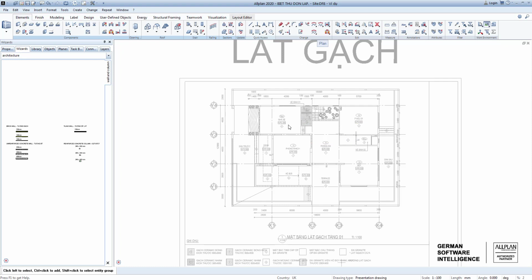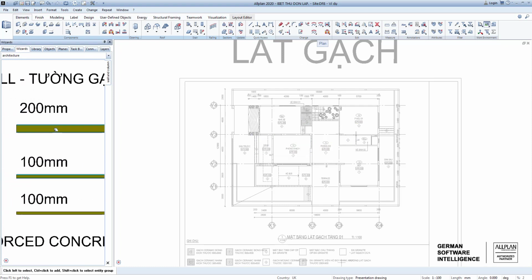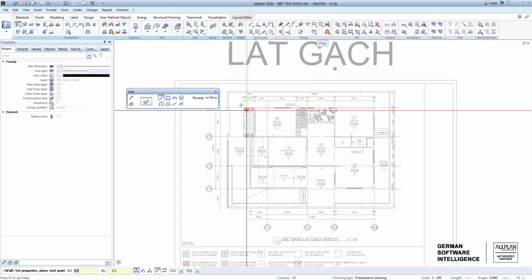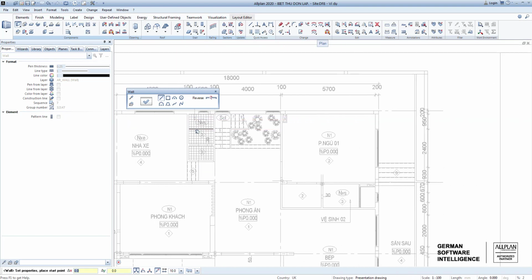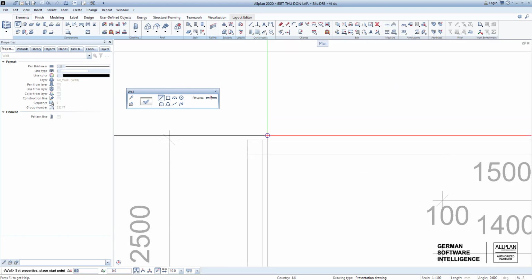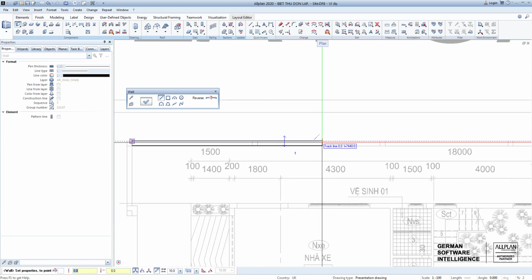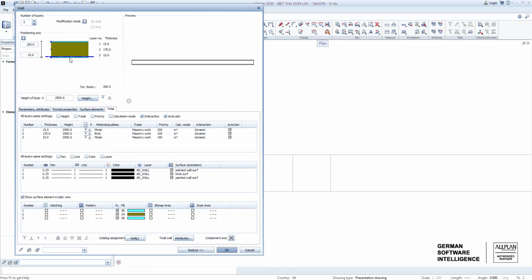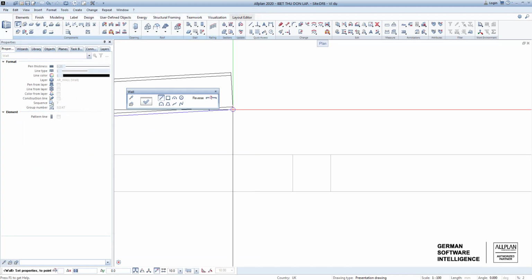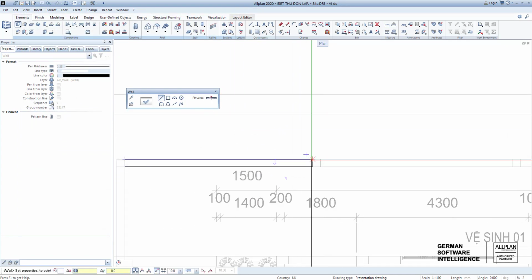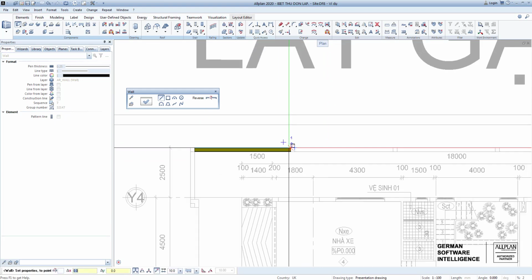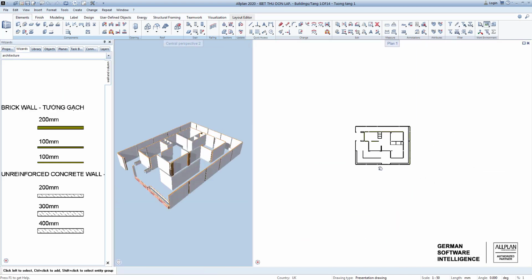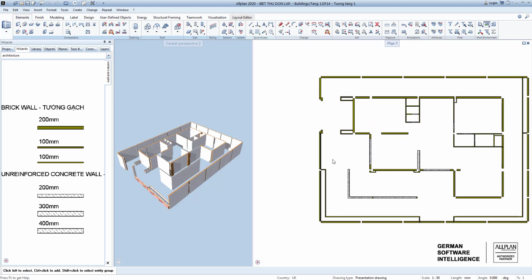You can now start creating walls. Select the existing wall, right-click and choose Match to copy the attribute. For example, you erect a brick wall. Here we can adjust the positioning if not appropriate. And finally, you will build the walls and columns system for a story.